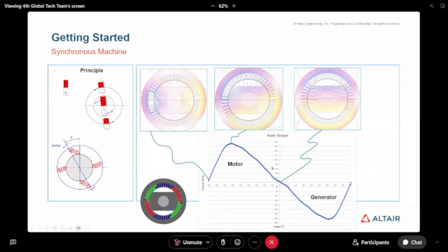So this is exactly what we call a reluctant torque, the interaction between the magnetic field on the stator and the reluctance variation on the rotor. We can see the same thing in a permanent magnet machine with the cogging torque, which is the interaction between the magnet and the reluctance variation due to the stator slot. So when we control the synchronous reluctance machine, we look for the angle that gives the maximum torque.